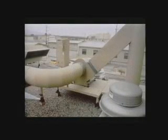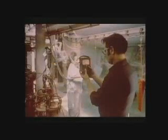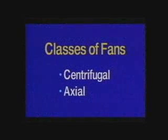When choosing a fan, be sure to select one which will provide the necessary static pressure and volume flow rate. Remember, though, the volume flow rate is always determined by emission control requirements at the hood. The fan is to serve the hood's need, not vice versa. Fans are divided into two main classifications: